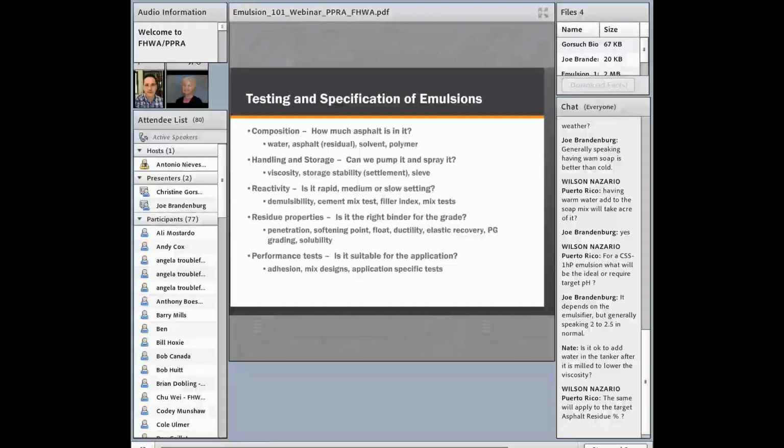So this is like the abrading action of traffic on the seal. So you're looking for moisture resistance here and the asphalt content. So depending on your application, there's a number of performance tests that are used to determine whether or not the design and the emulsion formulation that you've come up with are going to perform the way that you need them to.